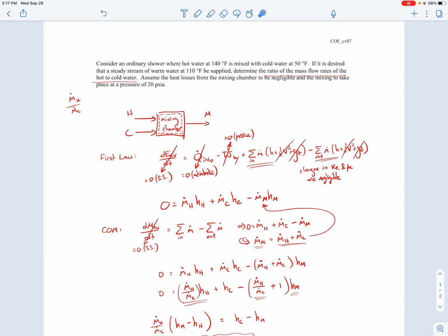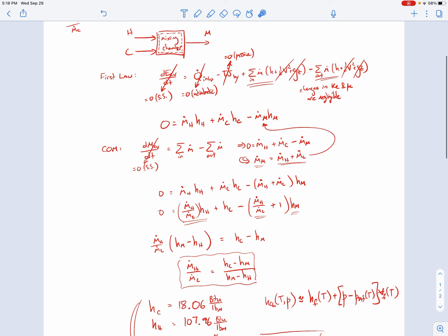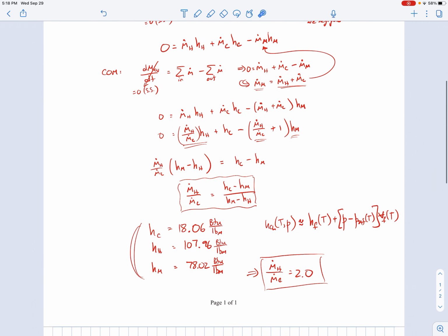140 degrees coming out of a hot water heater is pretty hot. In fact, normally you wouldn't have your hot water that high. You could risk scalding yourself if you don't have any cold water to mix with it. So normally you wouldn't put your hot water quite so high. It'd be closer to maybe 115 to 120 degrees Fahrenheit at most, typically. Otherwise you could risk scalding yourself.